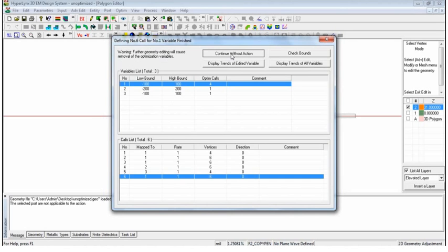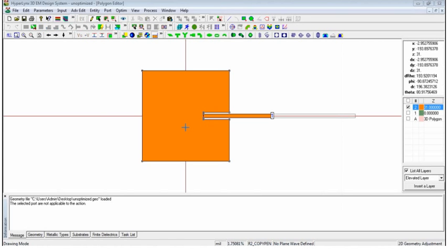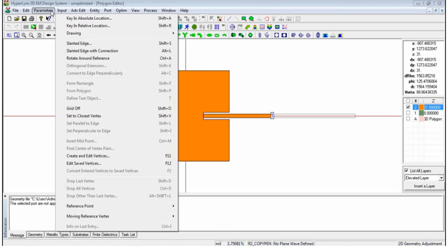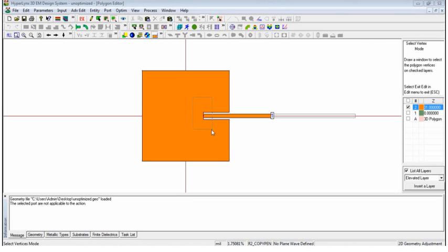Okay, so we have defined a variable which is mapped to particular variable 1, and it is for the second sort of vertices. The next thing is I want to define the bounds for that particular variable also. So I go to Optim again, or basically you just select the vertices again, you window it, go to Optim, variables for selected objects again.